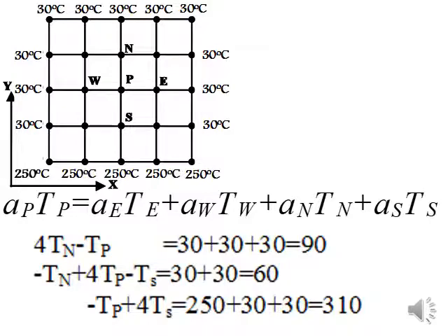And the third equation, now you go to your southern boundary, so that your Ts is subjected to 3 known values: the background temperatures on the east and the west, and your southern boundary condition, 250, and Tp is still involved. So you can cancel each equation by the next one, so that you can get the linear set of equations to be solved.